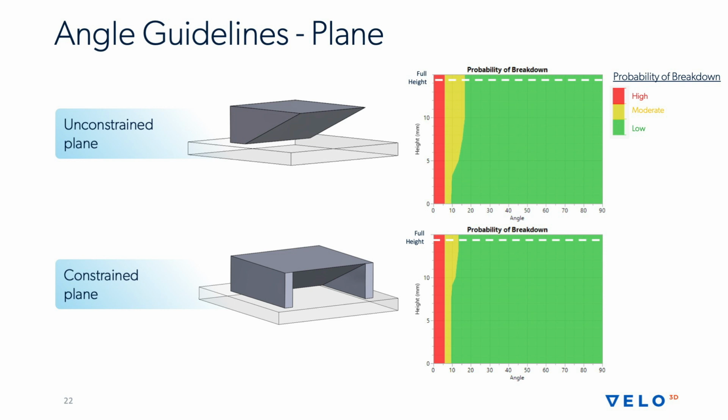And this is mostly because the thermal behavior is different for the downskin process than it is in the middle. And so the first parts that will warp and distort are these edges. And you'll see that for the constrained case, where the walls are acting almost as a support structure, if you want to think about it like that, it keeps everything more tidy and more constrained, and that yellow area here disappears and shoves over, and so you have more safe area when you're talking about printing really low angles like the 10, 20 and 30 degree ranges.